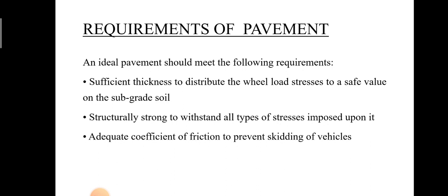That is, an ideal pavement should meet the following requirements. First of all, a pavement should have sufficient thickness to distribute the wheel load stresses to a safe value on the subgrade soil, and a pavement should be structurally strong to withstand all types of stresses imposed upon it. Then the pavement should have adequate coefficient of friction to prevent skidding of vehicles.